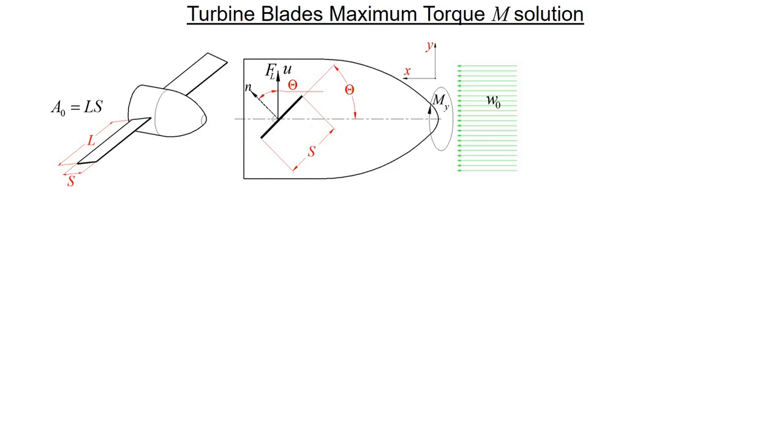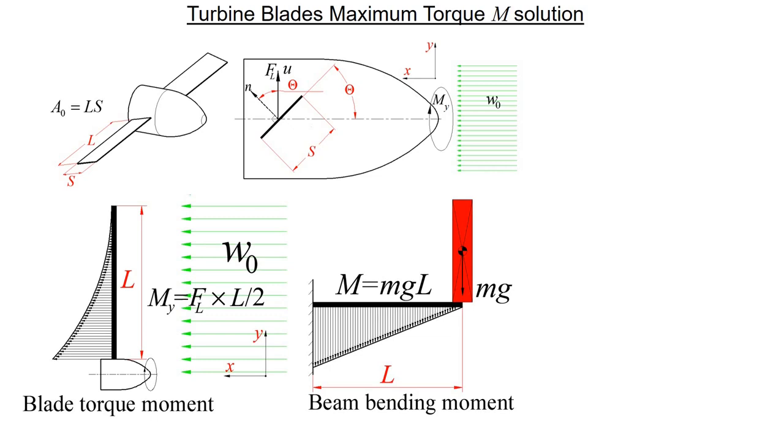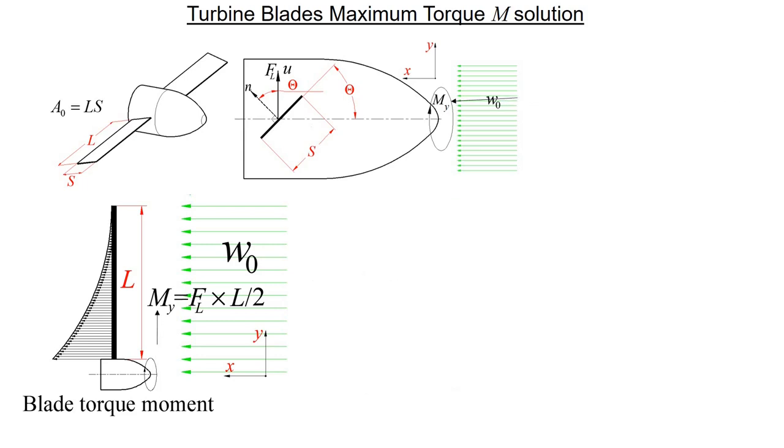In beam mechanics, concentrated load is calculated according to the equation shown in the picture. In our case, with velocity, we have uniformly distributed the lifting force of wind over the entire blade length, capital letter L, shown in the picture here. Torque force is distributed according to a parabola equation, and the total turbine torque force for a k-blade turbine is equal.